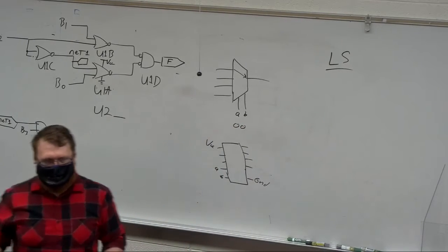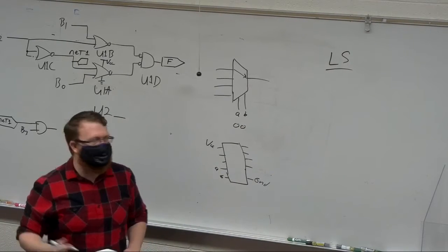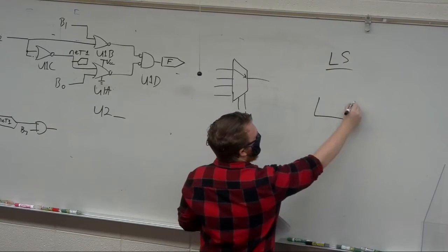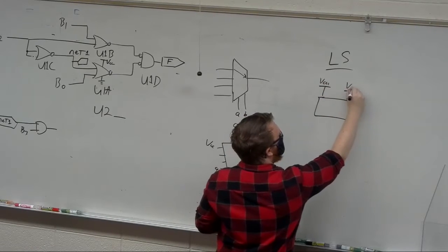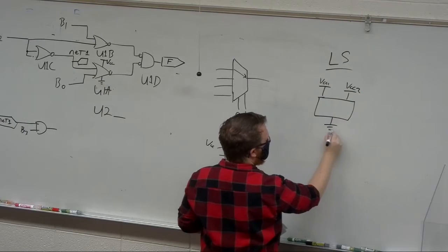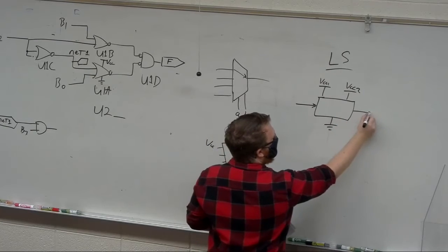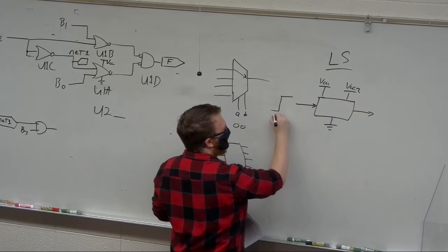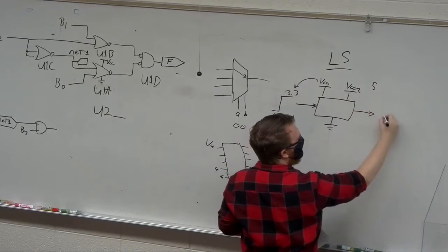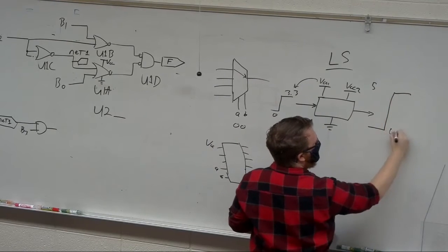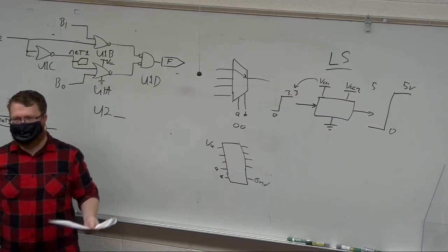It's not always possible. You can use what's called a logic level shifter that will take, well, let's call it just a black box. It's going to have 2 different powers. It'll have VCC1, VCC2, some common ground usually. It might have separated grounds, and then an input and an output. And this may be 0 to 3.3 for VCC1, and then VCC2 may be 5 volts. And so then it's going to step it from 0 to 5 volts.